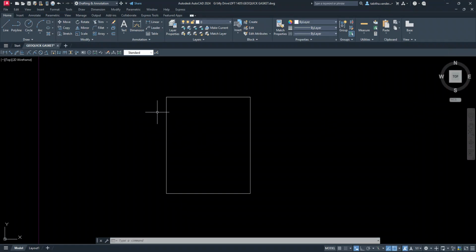So this is our introduction to the offset tool. To get into the offset tool, I'm going to type in O, the letter O, not 0, the number. I'm going to type in the letter O, enter. I'm in my offset tool now. Now, I'm going to always read the instructions that I see before me in the dynamic input. It says specify offset distance. This bottom line is going to be projected up 2 units. So when it says specify, that usually means type something. I'm going to type in 2 and then enter.